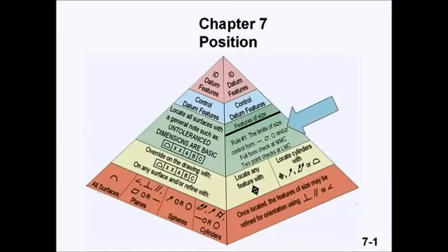We now know that any surface may be located using profile of a surface. We also know there's a special group of features known as features of size. The size and form of these features is controlled by the limits of size in accordance with rule number 1. If the feature of size is a cylinder and is coaxial to a datum axis, we will see in the next chapter that there are several ways to control the location. This chapter shows how to locate these features of size using the position tolerance.